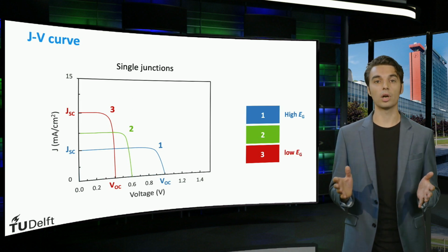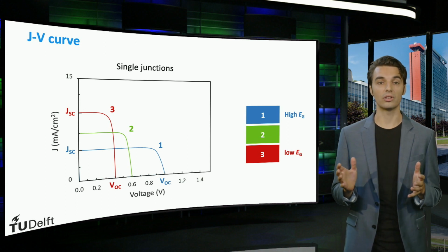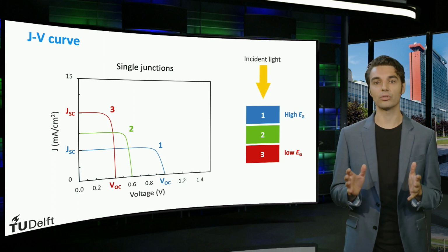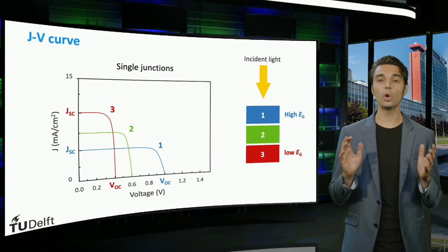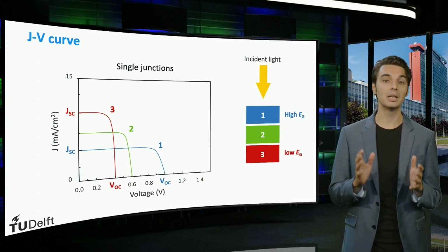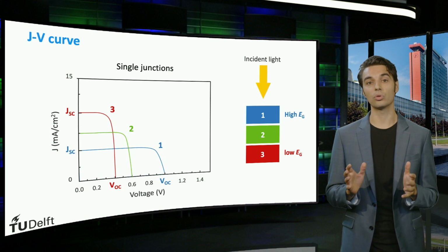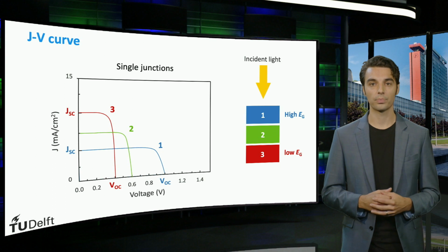The spectral part with the most energetic photons, like blue light, has the smallest penetration depth in materials. The junction with the highest bandgap therefore always acts as the top cell. In this way, the most energetic photons are absorbed with minimal thermalization losses, and the top junction is effectively transparent to a large fraction of the spectrum with photon energies below its bandgap.